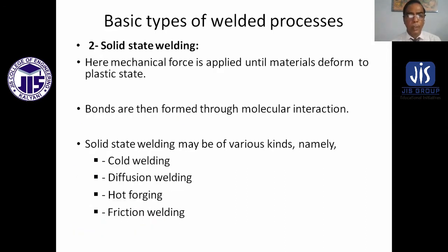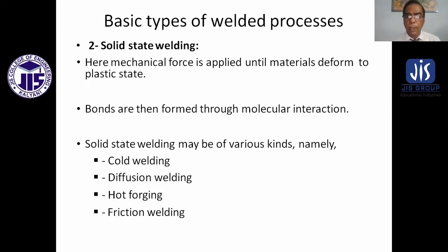In solid state welding, mechanical force is applied until the material is deformed to a plastic state. Bonds are then formed through molecular interaction. Solid state welding may be of various kinds, namely cold welding, diffusion welding, hot forging, friction welding.